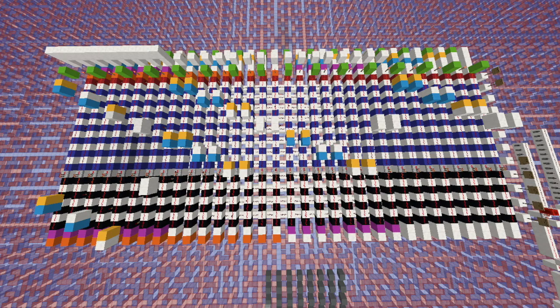like if we're shifting left versus shifting right. By default, all of the barrel shifting is going to be going on at once, so when we OR them together, it's going to make a rotate, and sometimes we just want to be doing the right shifting part of it, and sometimes we just want to be doing the left shifting part of it. So we're going to need to decode those last 2 bits to determine which ones of those functions we actually do. And this turns out to be pretty simple because all we really need to do is just connect up some control wires.